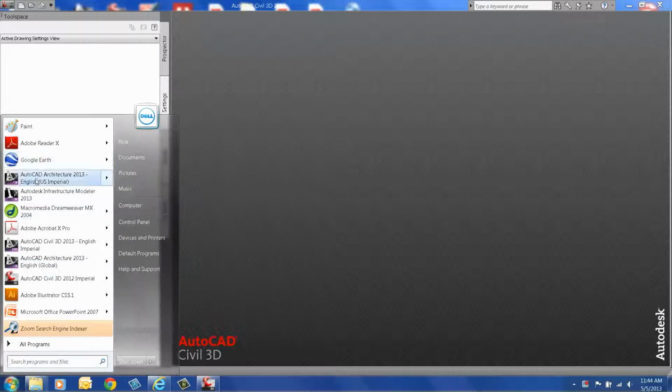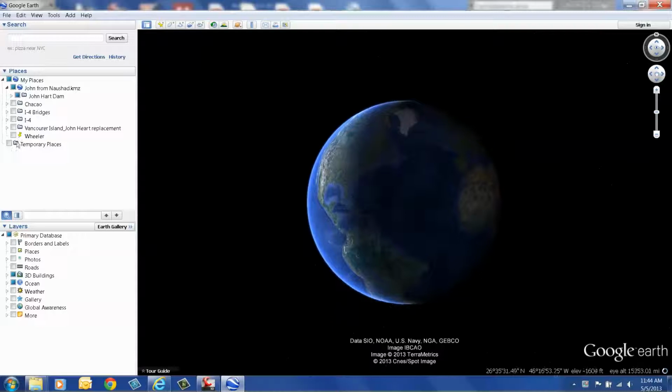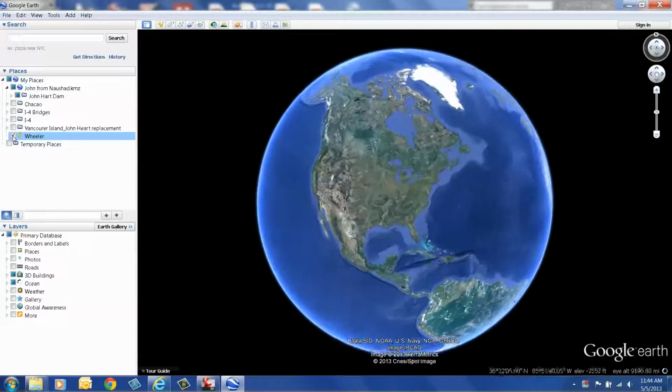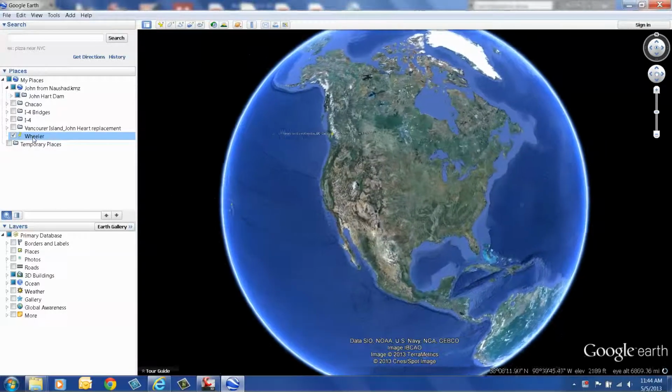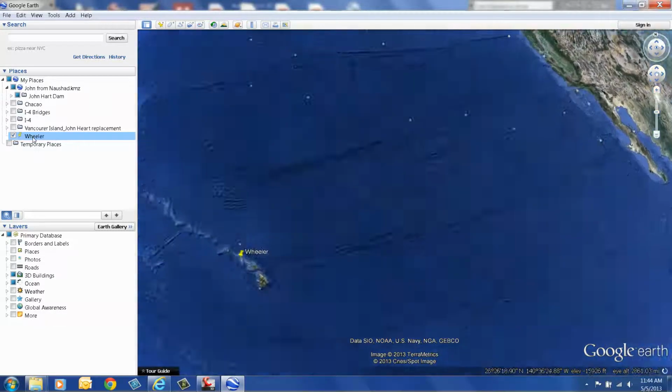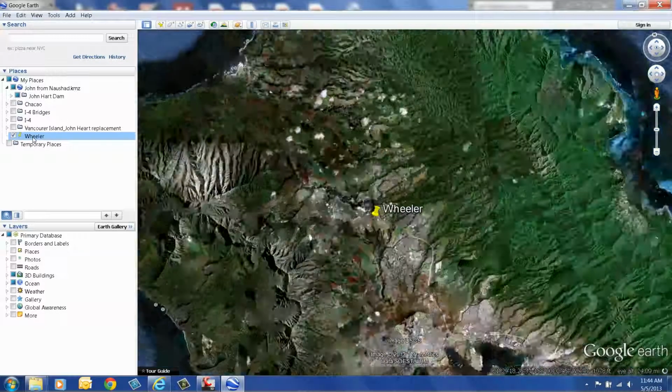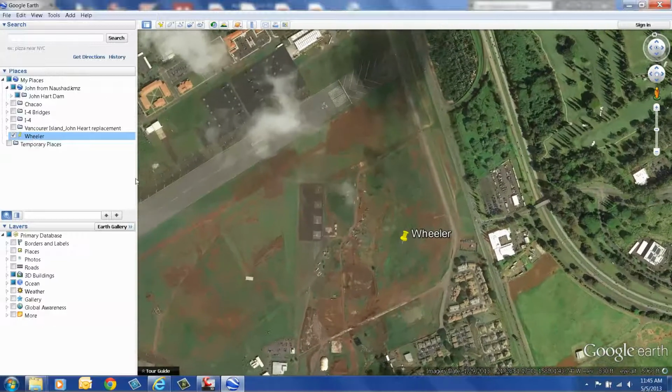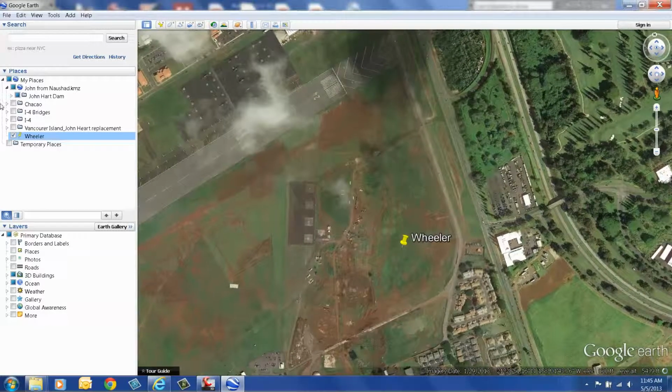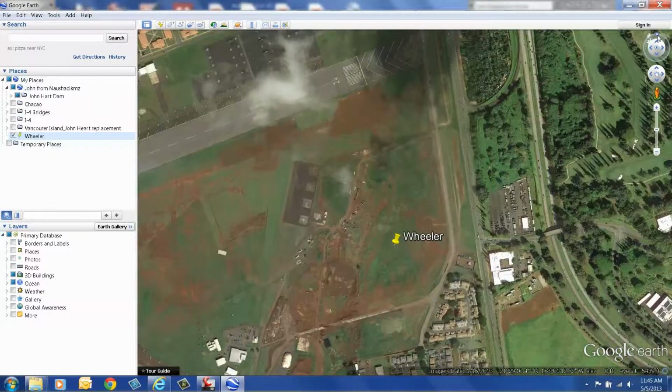But basically what you do is you go to Google Earth, and then from Google Earth you go to your project specific location, and in this case we have an inactive project that I'm using as an example because I have a lot of the data we received from the design firm. So when you click on your pinned area, you want to maybe fix the north arrow just a bit so that it's facing north. And as a personal preference of mine, I always turn off the pin because I don't want it to show up on the image when I download the image too.